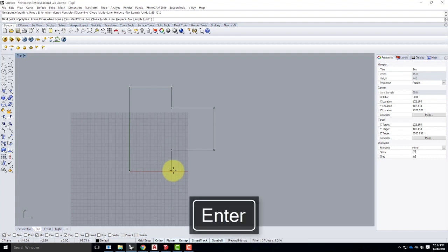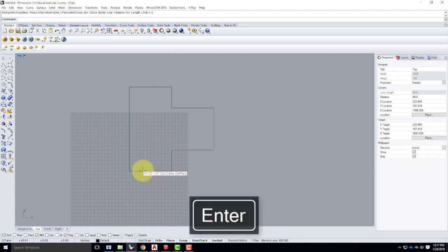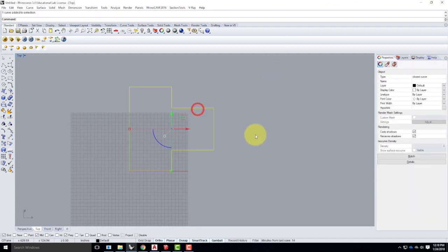Now I could switch back and use an absolute coordinate here. The absolute coordinate of this would be just 12 feet, 0, no at sign, because it's relative to 0, 0. I could hit enter. And then I could finish by typing 0, 0, or I could close my polyline by typing C for close, or clicking the close button. Just means it closes it. So C, enter, closes it. Doesn't matter whether I type 0, 0, or I type C to close it, or I click on the endpoint of my drawing.